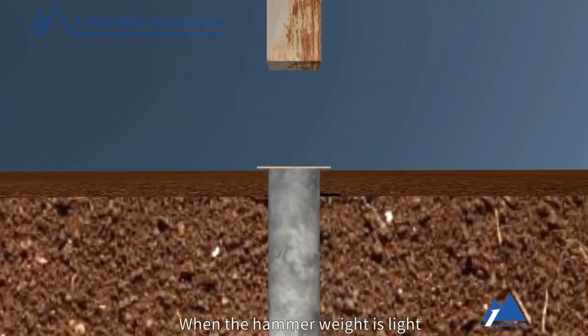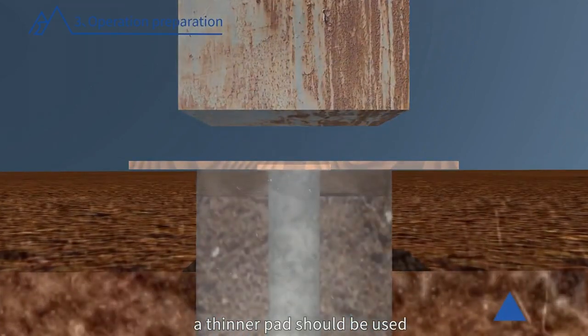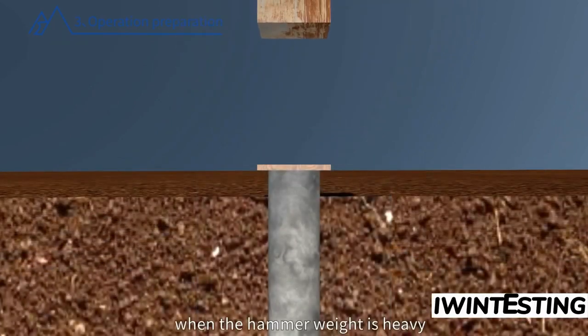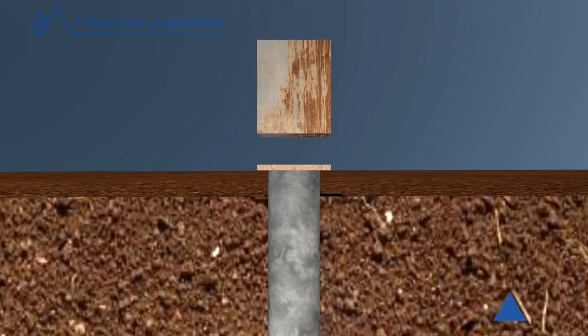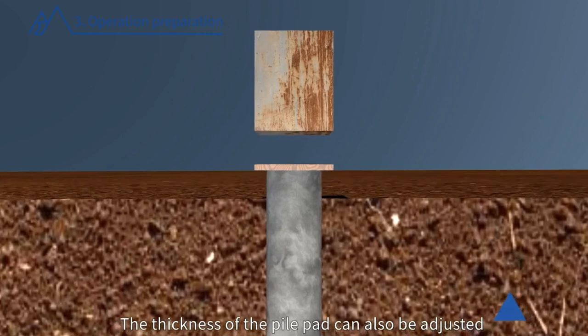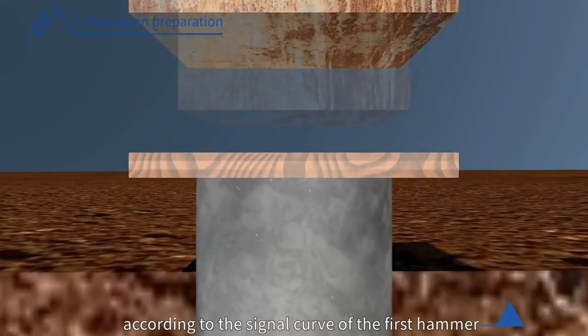When the hammer weight is light or the hammer fall distance is low, a thinner pad should be used. When the hammer weight is heavy or the hammer fall distance is high, a thick pad should be used. The thickness of the pile pad can also be adjusted according to the signal curve of the first hammer.